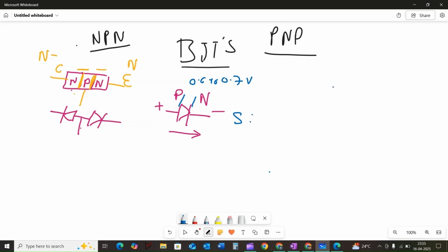If the polarity of the silicon diode is reversed, that means the positive terminal is connected to the cathode and the negative terminal is connected to the anode, it enters into the reverse bias mode and is essentially off unless the maximum reverse voltage is exceeded. Understanding forward and reverse bias is crucial for transistor analysis because it determines the transistor operating region, that is active, cutoff and saturation.